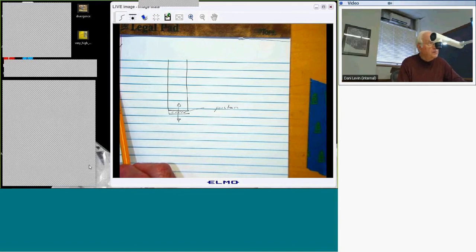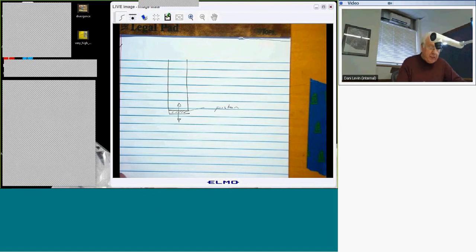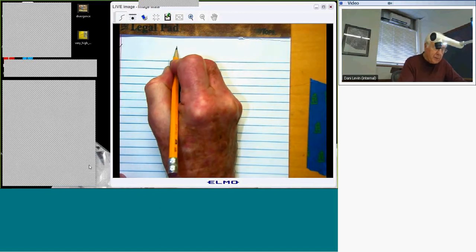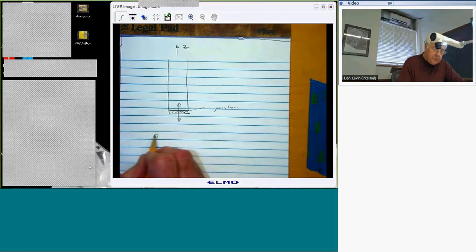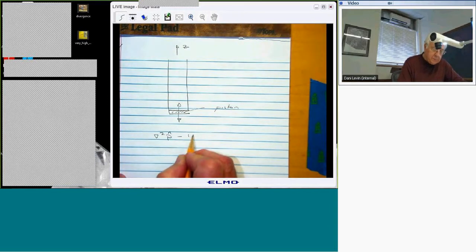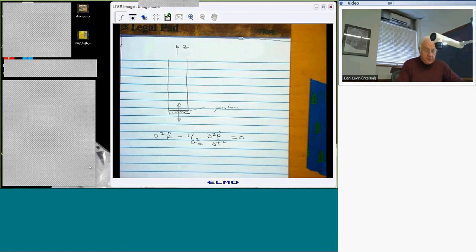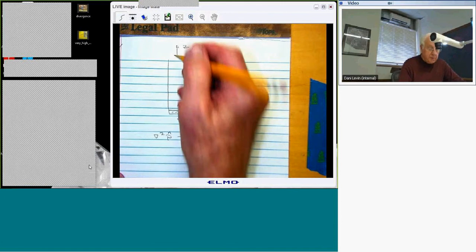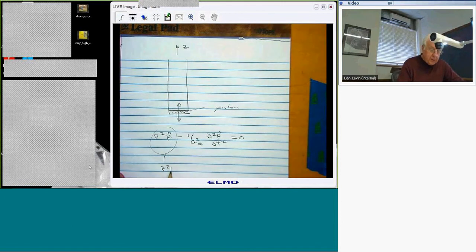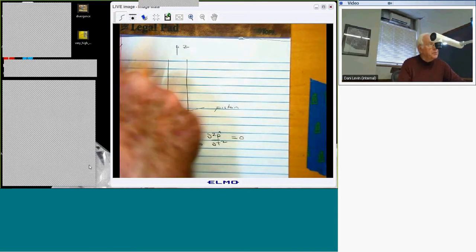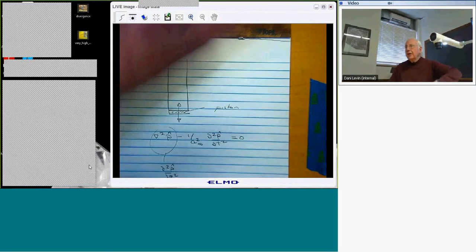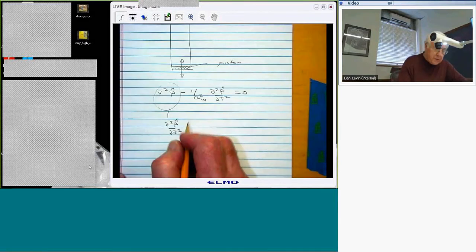I have to solve a suitable equation. And if I think it's governed by the equation of acoustics, that means I'm going to call this, suggestively, the Z direction. I need to solve this equation, but it's basically now one-dimensional. So this Laplacian just gets replaced by a derivative in Z. I'm assuming nothing's changing with respect to X and Y because this is such a narrow channel. All the significant changes are in the Z direction.